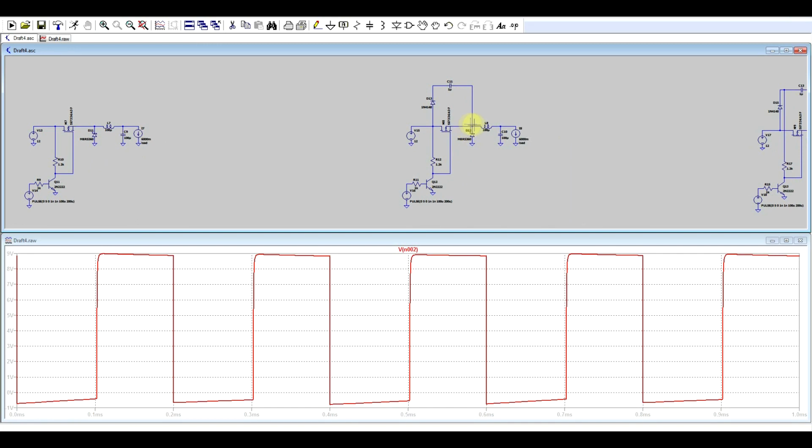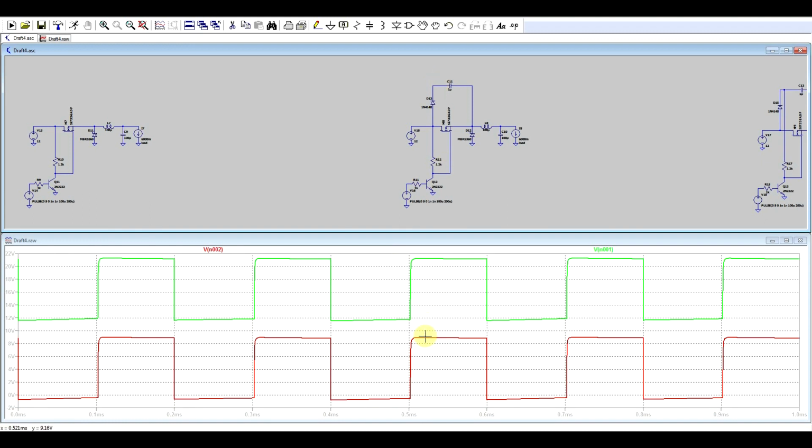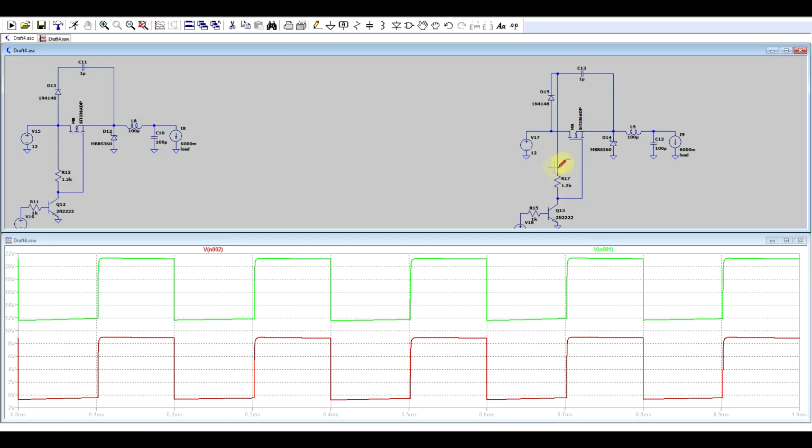And if we look at how this works, we can see that the voltage in the switching node goes up to 9 volts, but the voltage on the capacitor, at the moment when the voltage in the switching node is high, gets up to 21 volts. So plenty enough to drive the transistor. So there's just one small modification that needs to be done to the circuit, and that is connect the high side resistor to this point. So to no longer drive the gate of the transistor from the supply voltage, but rather from this bootstrap voltage.